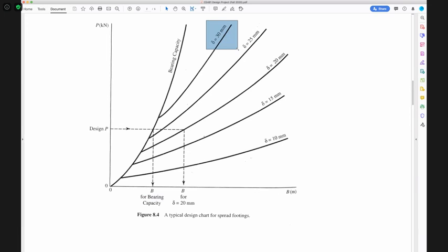It'll be consolidation settlement for the clay site. It will be the Schmertmann method for the sand site. And you'll have 3 curves for each of them, called out similarly to what is requested in the assignment. And these require 5 data points per curve. And 5 data points is a low enough number that you can do a bunch of this stuff by hand.